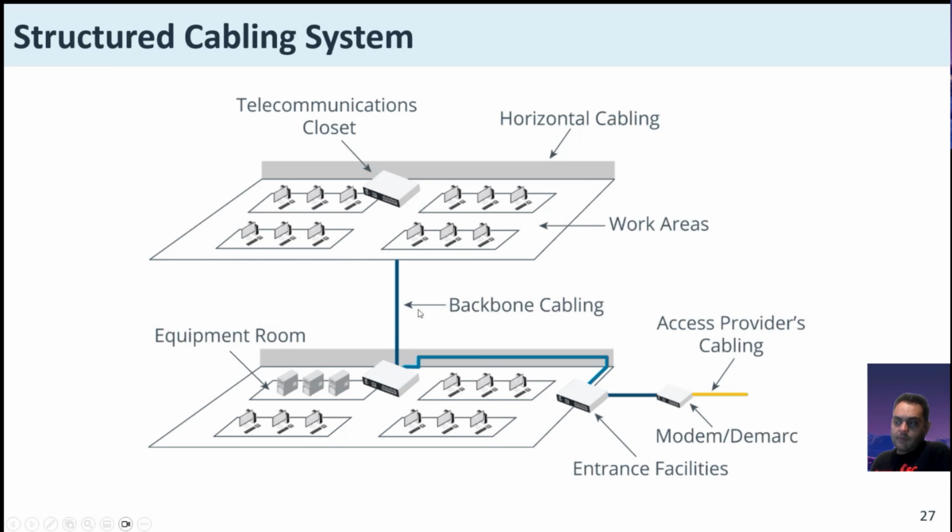Backbone cabling, which is this here, dark blue, connects horizontal cross connects, HCCs, to main cross connects, optionally via intermediate cross connects. These can also be described as vertical cross connects because the backbone cabling is more likely to run up and down between floors, first, second, third, basement. I'm really hoping that we can get you guys into the Carlisle executive office so we can show you how those are actually run out.